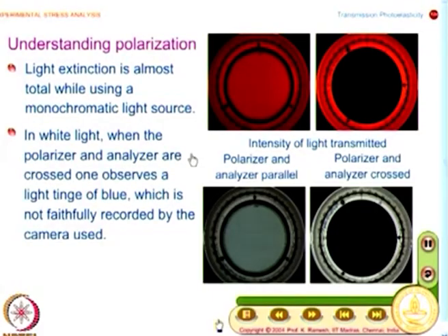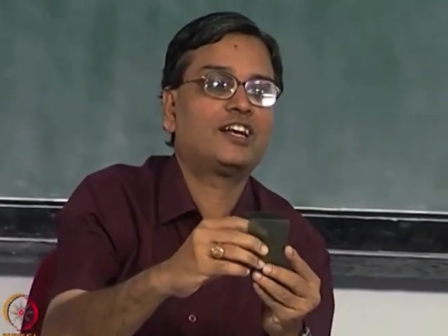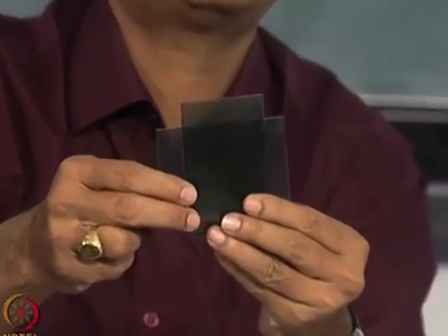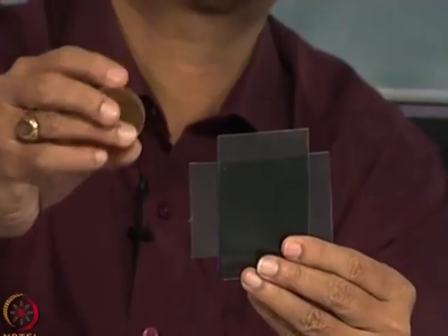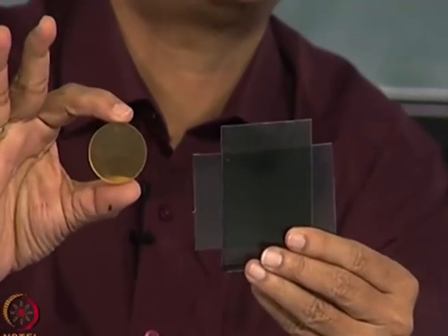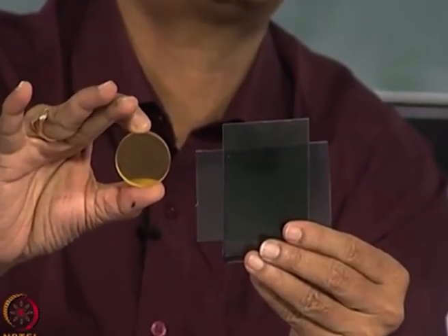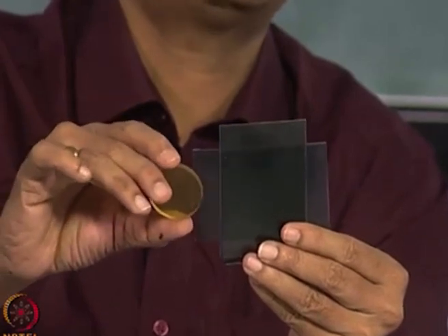I will also try to show a simple experiment for you to observe. I hope this camera faithfully records it. Because I have a light here and the light falls on this, I can see it, but I do not know whether it will get fully recorded; let us try. What I have here is the model. I have these elements put perpendicular, so this is dark, and I have this model, which is photoelastically sensitive and made of very soft material. I can apply the load with just a slight compression to see fringes, it is so sensitive. I am going to insert it in between.